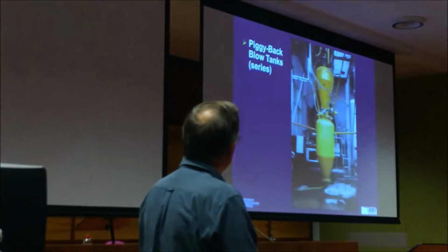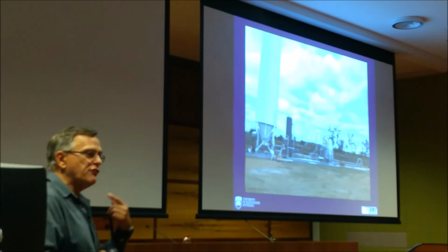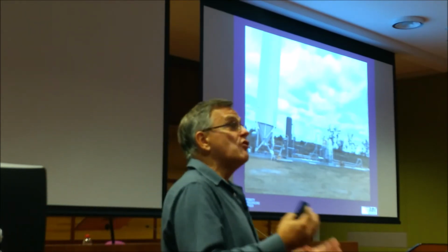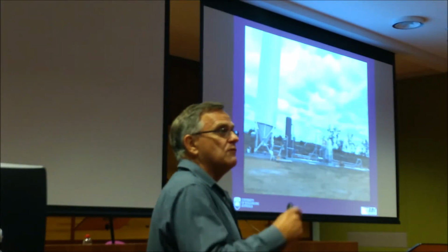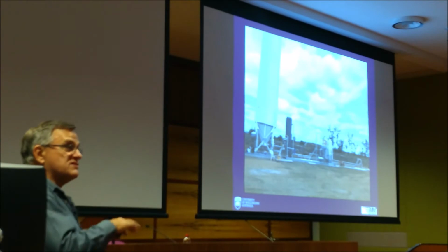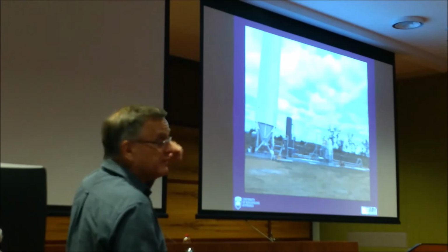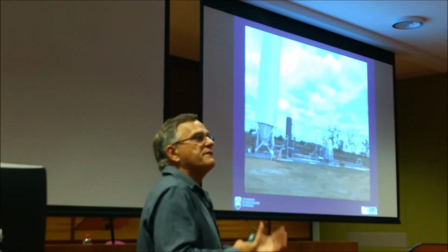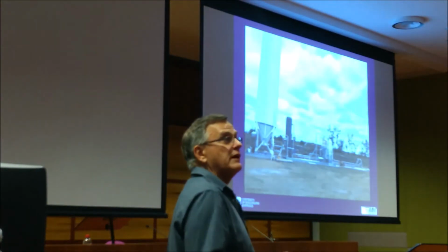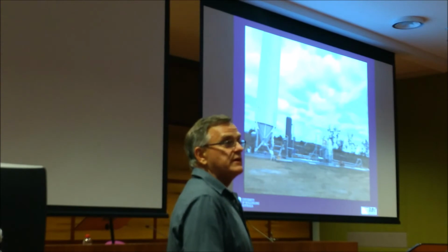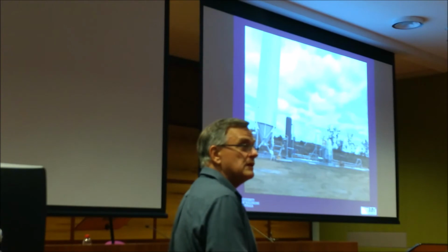So this system here, we actually used a combination of pressure vessel and rotary valve to give you a feed rate accuracy. So we're using rotary valves in application not designed for this sort of service. So there are tricks of how we pressure balance across the valve to do that. Because valves are generally up to 100 kPa, but this system with a rotary valve is running up to 500 kPa, no problem. But you have to know what to do with the pressure balancing. Can be all done if you work out with all your basic engineering principles. And we'll do a bit of that after the break, some of the basic calculations that we perform for pneumatic conveying.